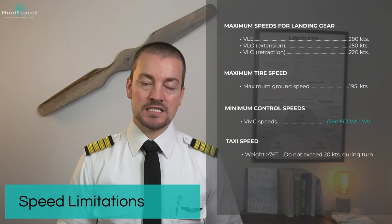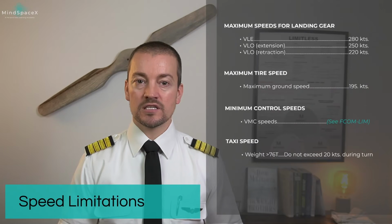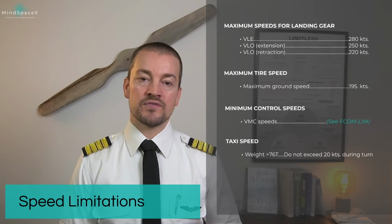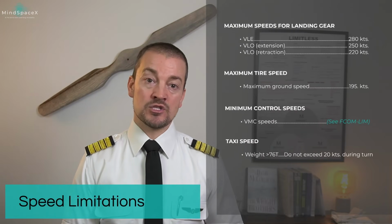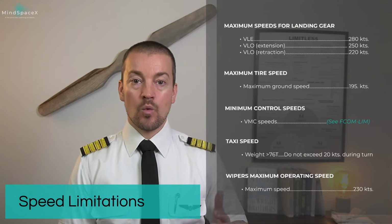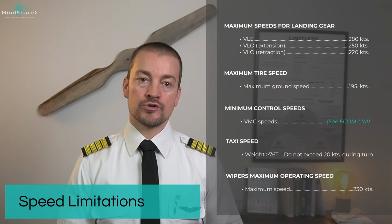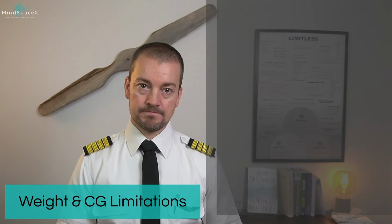Maximum taxi speed during turns should not exceed 20 knots if the weight of the aircraft is above 76 tons. That means you're maxed out on weight. And finally, wipers: maximum operating speed is 230 knots.